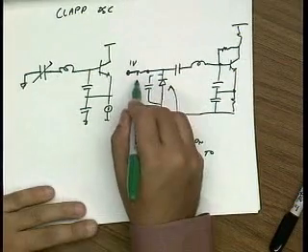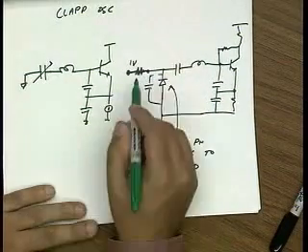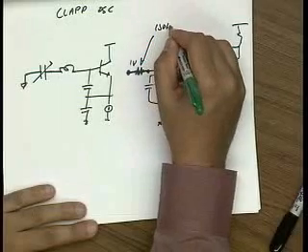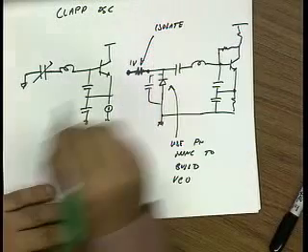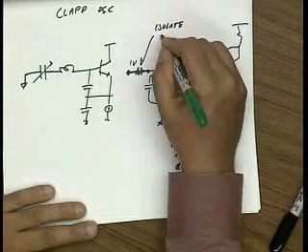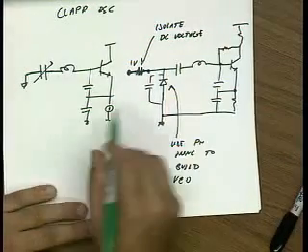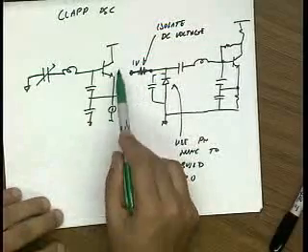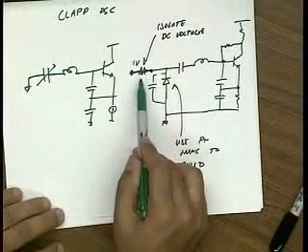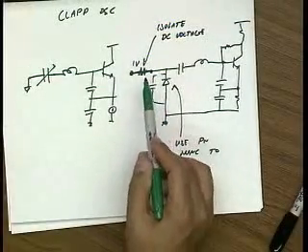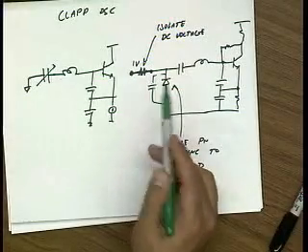I drew a bad resistor here, but this is a resistor. I need to isolate. Yeah, good point. So basically you want to isolate the DC voltage from the AC signal. Thank you. And the way you do that is you use a resistor here. Pretty large resistor, this might be a kilo ohm or something. You could also use a big inductor.